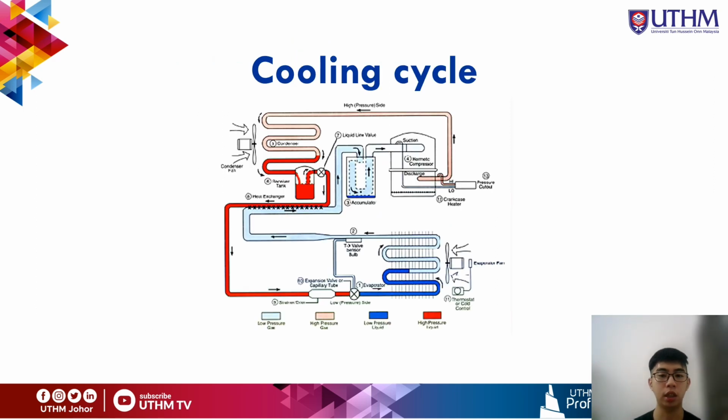For the cooling cycle of the air conditioning system, the compressor pressurizes the refrigerant gas and sends the refrigerant into the outdoor unit condenser coil. The larger fan pulls outdoor air through the condenser coil, allowing the air to absorb heating energy from the home and release it outside. During this process, the refrigerant is converted back to liquid.